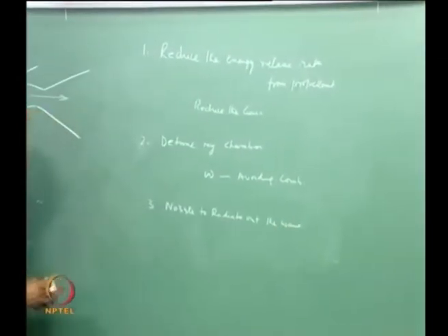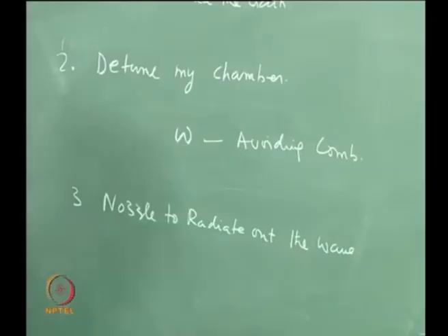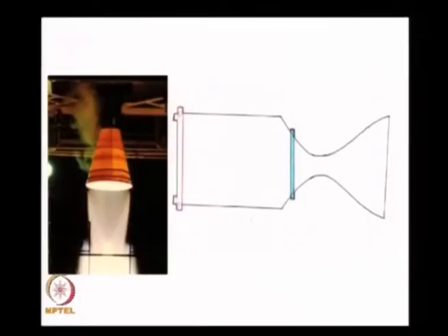Well, these are some correction strategies. You know, this figure shows an opening here, which means I slightly change the tangential mode, because the dimensions increase when I put a slot inside here. This has been effective in reducing the combustion instability of one of the Viking engines, a 60-ton liquid propellant rocket.